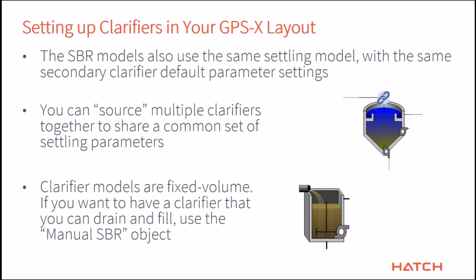Okay, so a few final thoughts on setting this up. The SBR models, sequencing batch reactor models, also use this same settling model, with the same secondary clarifier default parameter settings. So if you are using an SBR, in addition to all of the other sequencing stuff and aeration and mixing, there's a settling phase. And therefore, you also get settling parameters that you can use. And it's the exact same approach that I've just described to you.